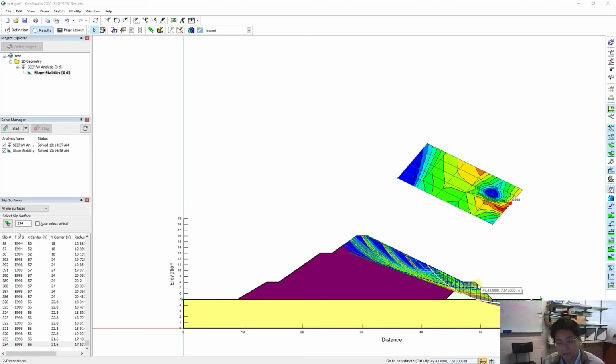The second thing that may be of interest to you is that the side road that we often use to reduce the slope and use for the dam repair is actually inside the reservoir. It should be on the other side, on the downstream side, where it is dry, and you can go over to observe, take a sample, investigate, drill a hole, anything like that.